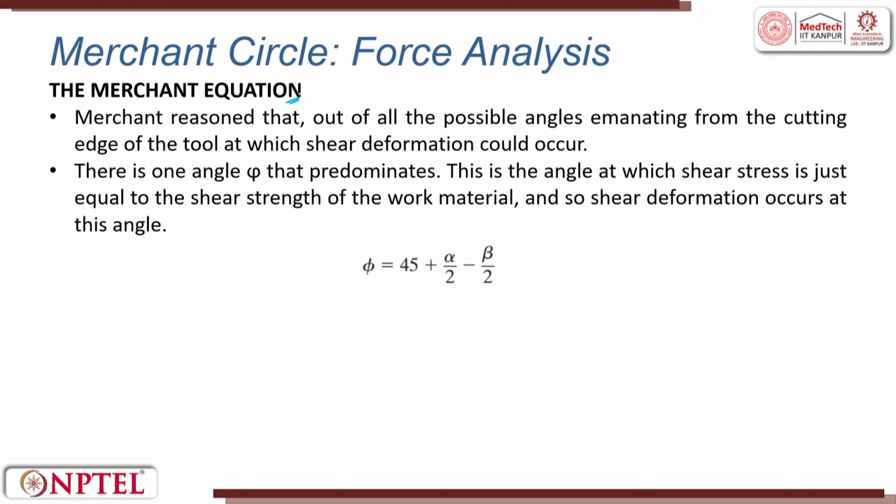So, the merchant circle equation can be finally written like this. Merchant reasoned that out of all possible angles emanating from the cutting edge of the tool at which the shear deformation could occur, there is one angle called phi that predominates as the shear plane.